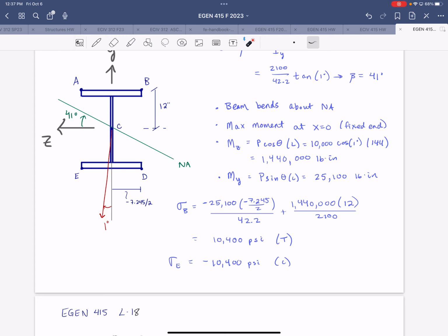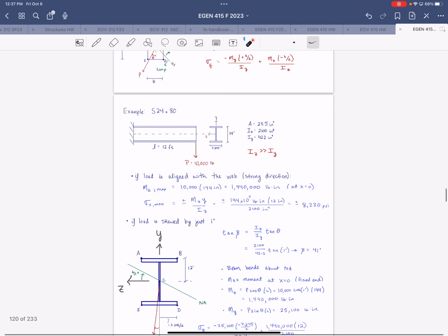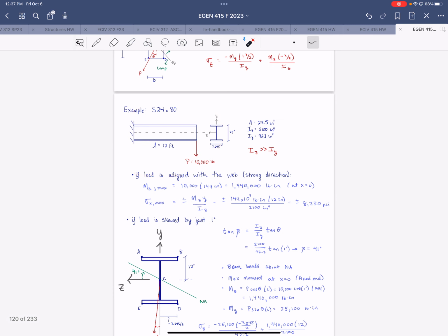So with Cash's question, is L the placement of the load where you're going to have the maximum moment? No, it's the moment arm. Right, okay. And then the maximum moment in the cross-section, that's going to occur where it's fixed, at the fixed connection? Yes, for this configuration and loading. A cantilever beam with a point load at the free end: maximum moment will be at the fixed support.